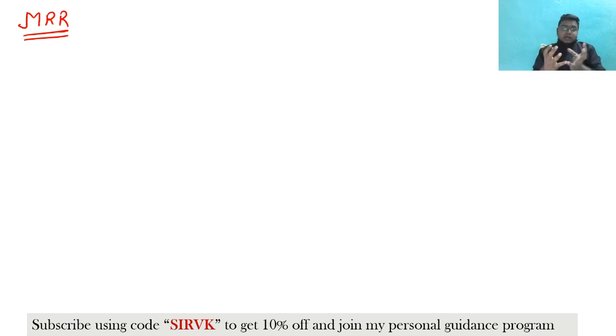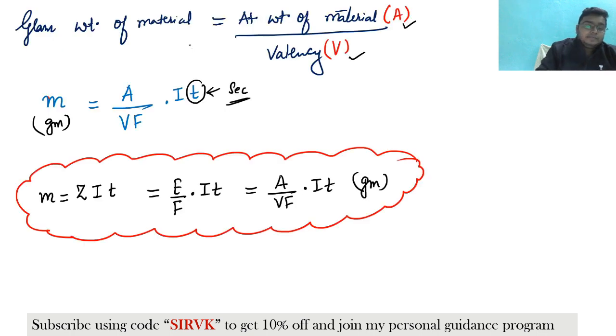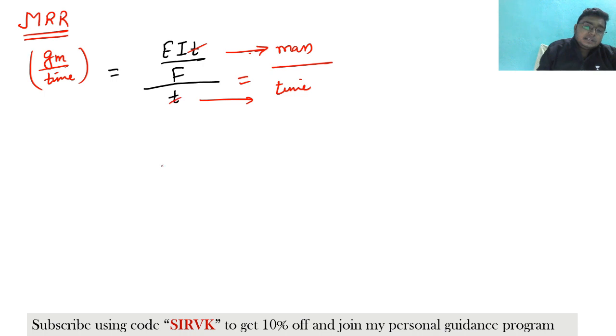Now if I divide any mass by the time, if I want to find the material removal rate, it tells how much material is being removed in how much time. So what I can write here is that if I want to find the material removal rate in gram per time, what should I do? I know that E I T by F is the mass, and this is in gram. Now if I divide this mass by the time, this is the mass and this is the time. Now if I see here, this T and this T will get cancelled out.